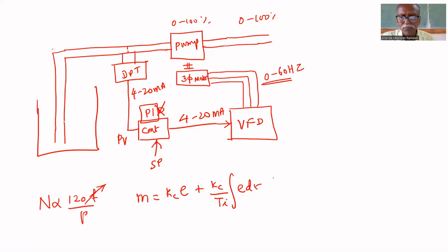That's why this plus bias. Always bias is required. Already we have discussed why bias is required. Suppose the car is running at 60 kilometers per hour. Are you giving any input, or because of zero error, you are not giving any input? You must give some input to run at 60 kilometers per hour. The same meaning here. If there is no error, at that time it should still give something to get the required output. For that, the bias is required. The controller will not find the bias. We have to find the bias. That bias the controller will add and give.